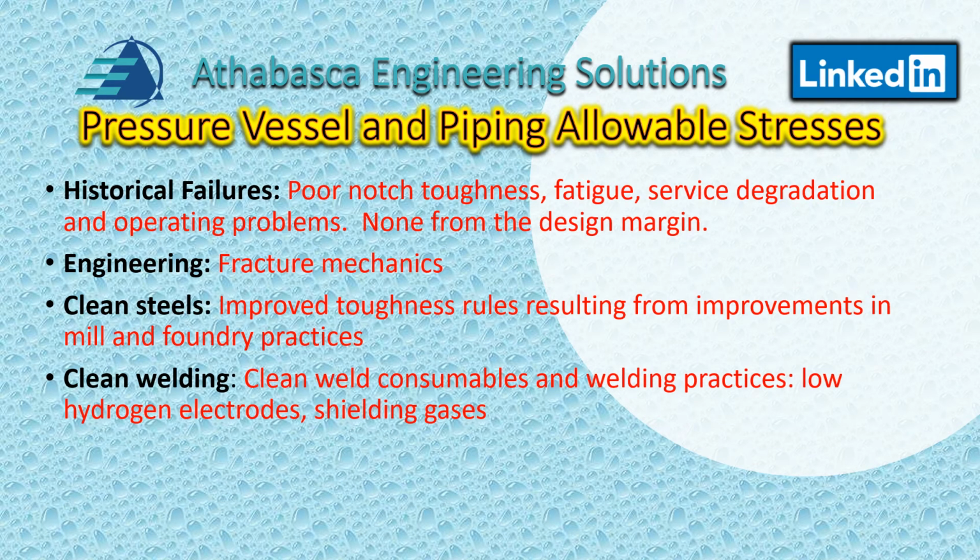And so also clean welding. Welding procedures have improved dramatically. So now we have very clean welding consumables made with high engineering controls. We've got great welding practices. We have very well trained people. And some of the big things are low hydrogen electrodes to reduce the chance of cracking, and shielding gases for prevention of contamination, and so on.